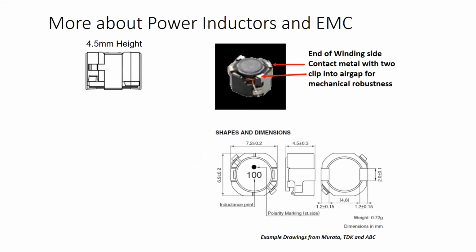And that's kind of the same principle that we have going on with the inductors, right? When we have these huge terminals or metal clips on some of these inductors, this does have that time varying signal on it. And we're now providing a path for that to get out because we're raising it above the board. We have that TV antenna effect. And so this becomes a very good antenna.